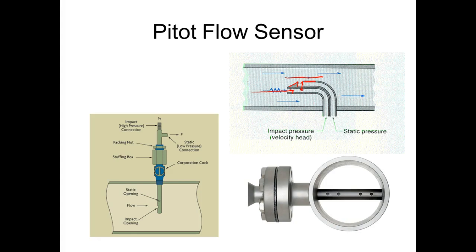Now, what's important about why they do this is because of what changes when you go up. Well, static pressure changes when you go up. So on the side of the airplanes, they have little holes that are the static ports, right? And then you have pitot tubes pointing out front, which take the flow, and that's what you're measuring. We call these things pitot statics.